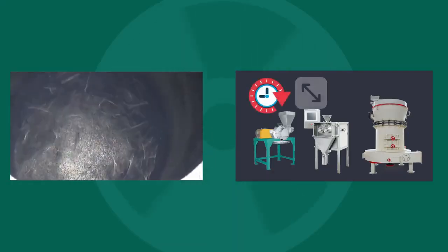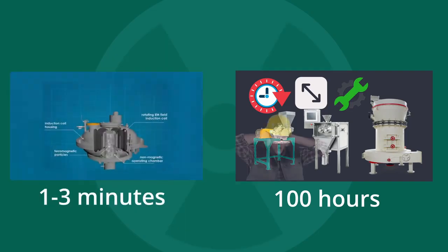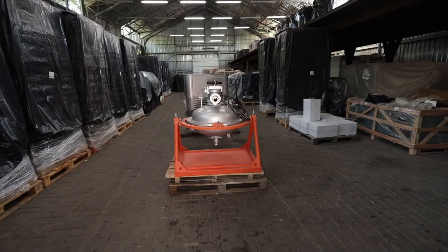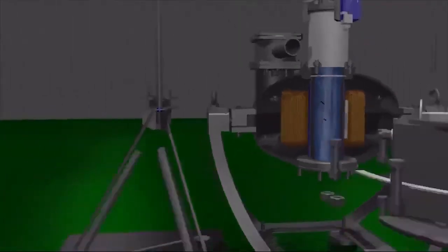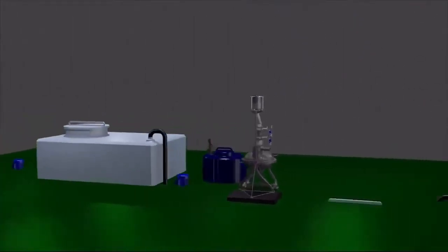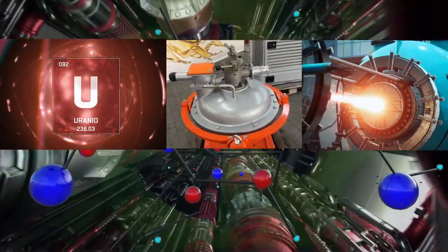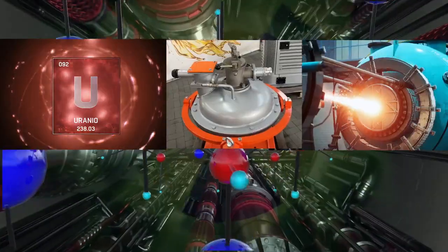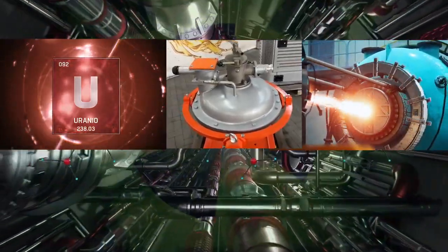Unlike ball and hammer mills, the constituents are processed in a matter of minutes rather than hours or dozens of hours. The device is compact by dimensions and easy to integrate into the existing process lines for reactor fuel production. The device can be used in various process diagrams related to production of nuclear fuel for fast and slow neutron reactors when finely dispersed powders and homogeneous mixtures are achieved.